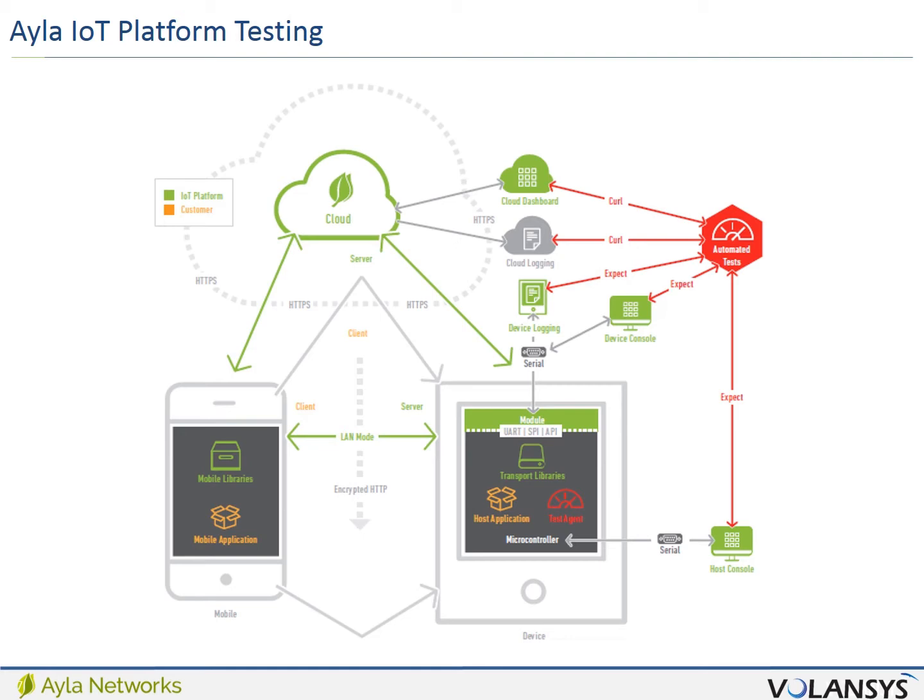For example, our module regression runs about 1,000 automated tests for 34 various platform combinations. With an average runtime of 6 hours, it constitutes about 6 days. To reduce this time, we run the regression on the test farm against all the platforms simultaneously. To run the automation, the firmware should have hooks for configuration, control, and logging, which could be collected by the test scripts from the module's console. Crash log capability is also crucial for debugging the failures.